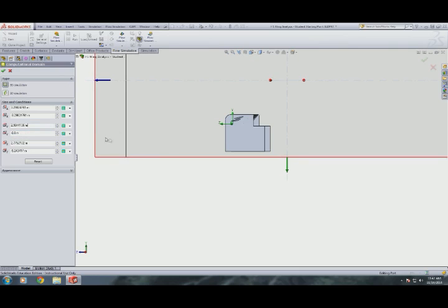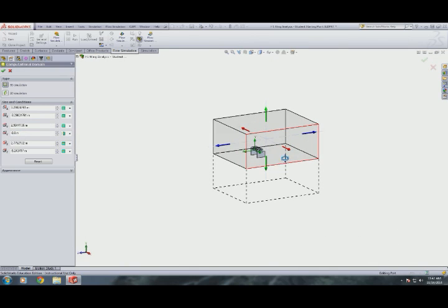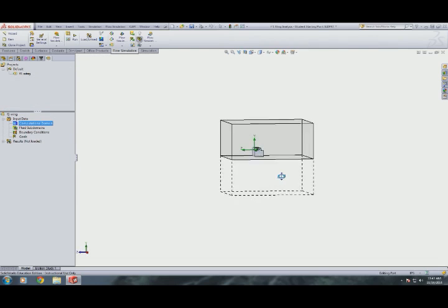Let's change that to a symmetry plane. This causes the ground to act like a reflection, meaning no flow can pass through it, which for other fluid reasons you'll learn throughout your education means that it is a ground plane. It's like emulating the ground right there beneath the wing. Alright, got that done. Set up symmetry plane.